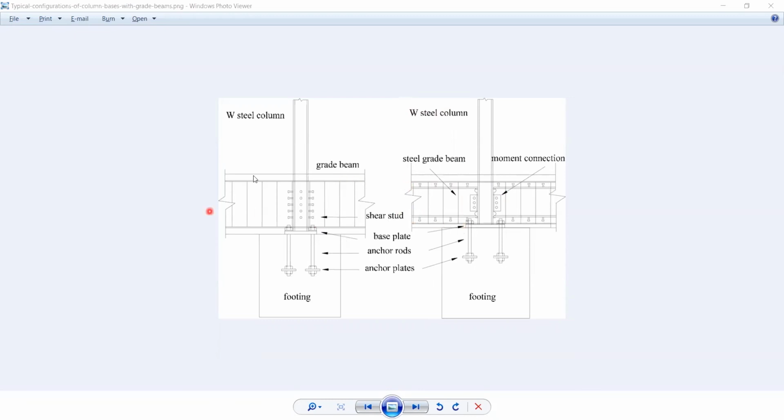Okay, here. The wide flange steel columns go all the way down and rest on what they're calling footing. So we're going to follow this detail. Obviously, we have a slightly different situation. We don't have this footing that's described here. We have these caissons. But we'll bring our wide flange columns all the way down, and they'll sit on top of the caisson. The grade beams are formed out of concrete, and we'll make this assumption that those are poured after these wide flange beams are set in place.